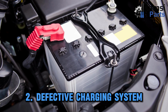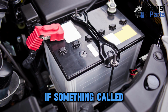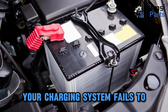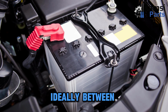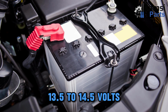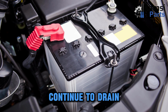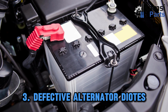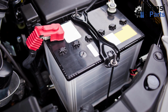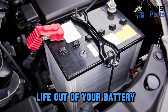2. Defective charging system. A car battery drains quickly if something called the alternator on your charging system fails to push out enough voltage, ideally between 13.5 to 14.5 volts. In this case, the battery will continue to drain even while the car is running. 3. Defective alternator diodes. Alternatively, the alternator could have defective diodes which would drain the life out of your battery.